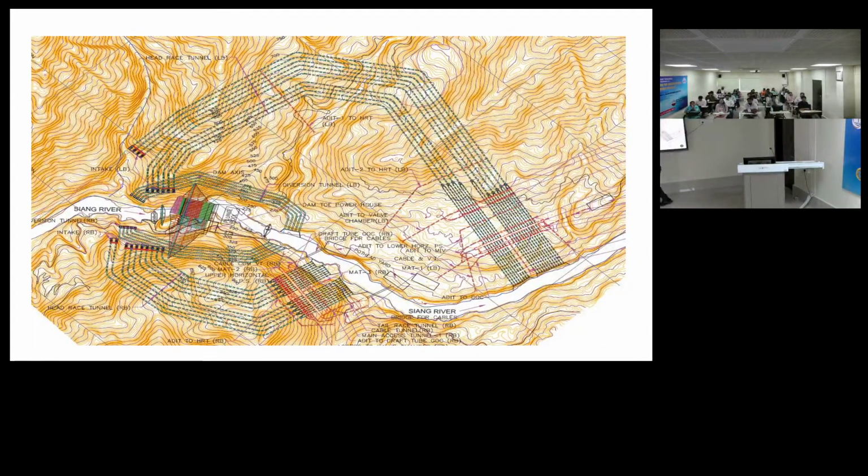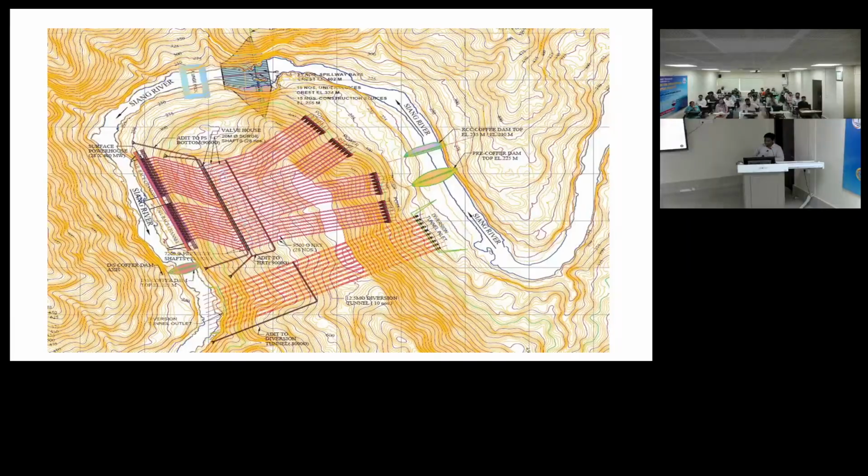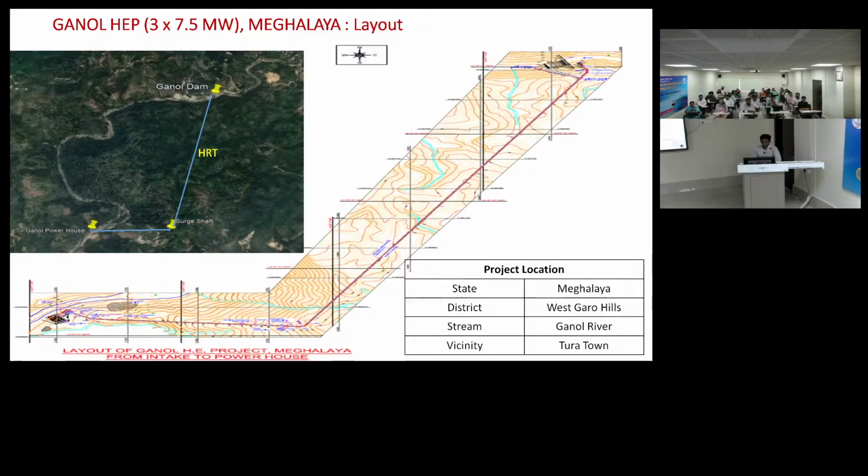So you can see if you want to have this main dam, there are small dams, these are coffer dams. So now the water is diverted from here. You can see the downstream coffer dam also. So now this area is completely water free, so we can have construction. But the layout, you can see the diversion tunnels are on both banks, whereas this layout, simple layout, right? Dam is here, everything is on this side only. So that's how layout finalization is also very crucial.